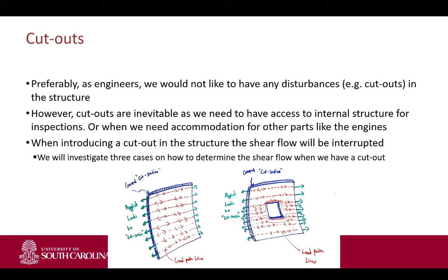Yes. I think I remember us talking about a situation where you put in a hole to simplify the shear loading or something like that, to make it easier. Is there any kind of situation like that where these two effects would offset? Where a hole weakens it, but then another one can distribute the load. I think you're talking about crack propagation. You drill a hole in it so that it doesn't. Yeah, that's different. In that case, what you're trying to do is to stop the crack from propagating.